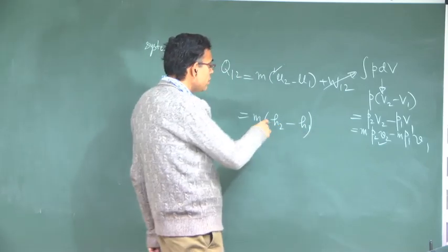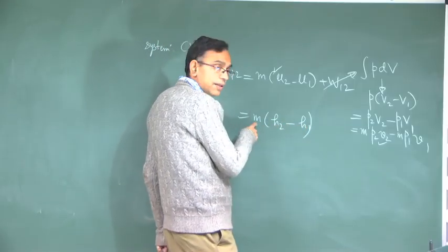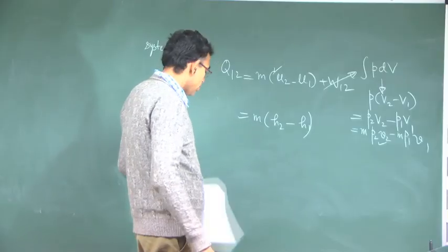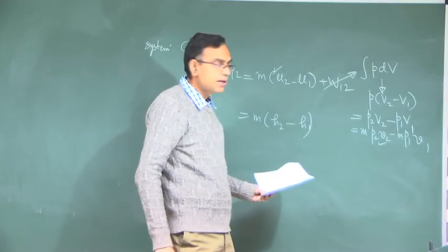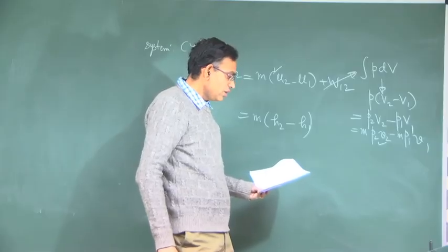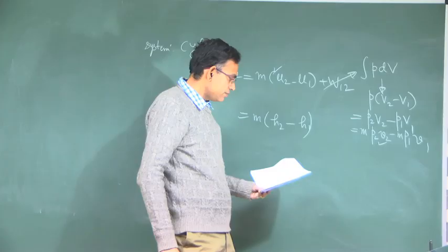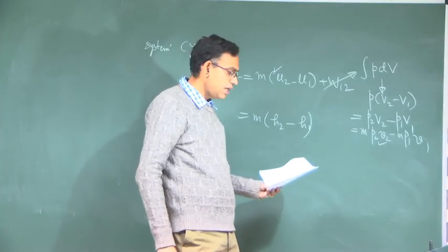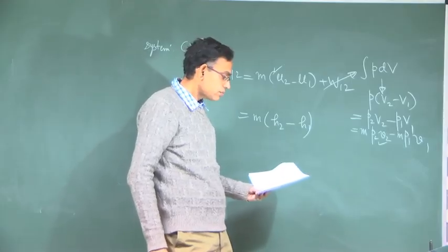So, by looking into the property tables, state 1 and state 2, you can get the enthalpy and then you will get m. State 1 is 700 degree centigrade, 10 MPa, it is defined by that. State 2 is 10 MPa and it is condensed to saturated liquid, 10 MPa and quality equal to 0, that is state 2.